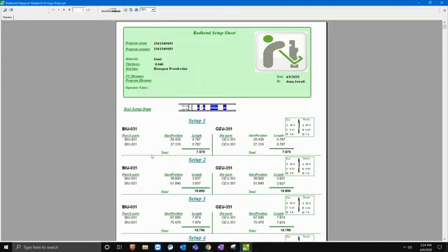It's giving me the punch parts, the start position, and then setup 1, it's giving me the die parts, or the bottom dies, and the start positions and the length of the bottom dies I'm using for my first setup. So even if you don't have a CNC press brake, you could still use this to set up a manual, non-CNC press brake, right?